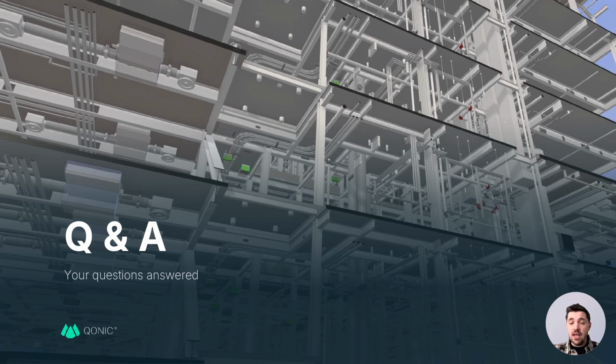So one of the first things to say is how do you bring information into Qonic? One of the first ways to do that is by dragging the models into the project dashboard in Qonic. You can bring in models that are IFC files. We work natively with that IFC information, which is good. And then you can bring IFC information out the other end of Qonic as well. The idea is that you shouldn't notice a difference. There shouldn't be any exporting mechanism that is effectively losing geometry or so on.